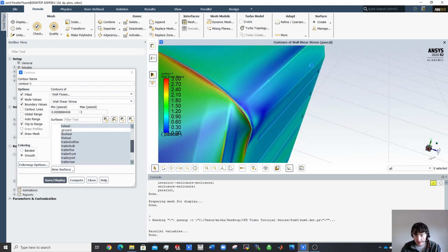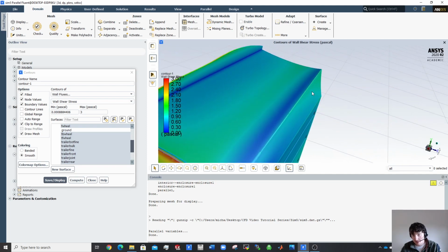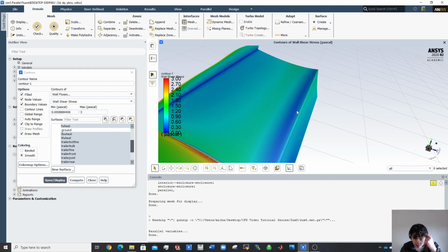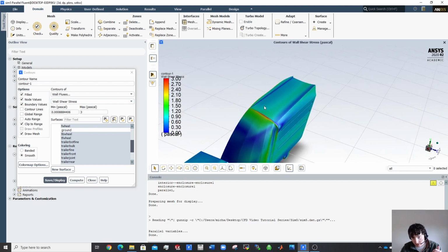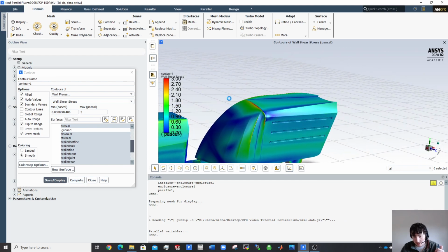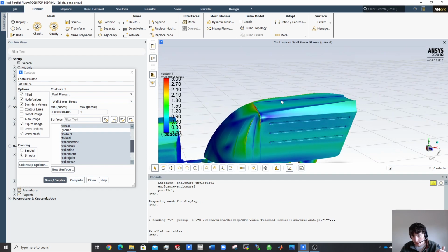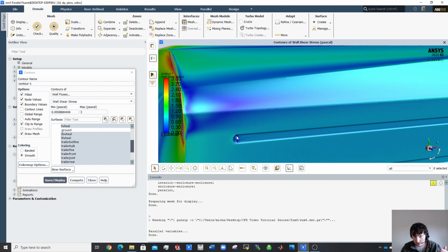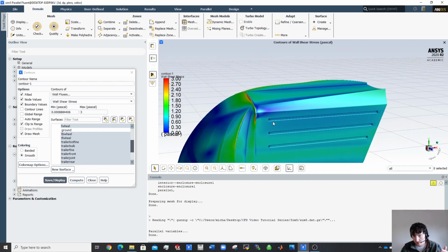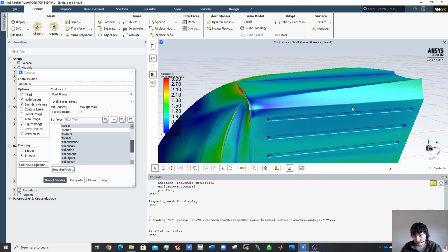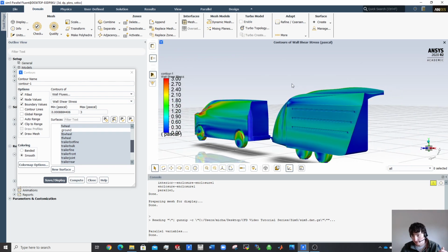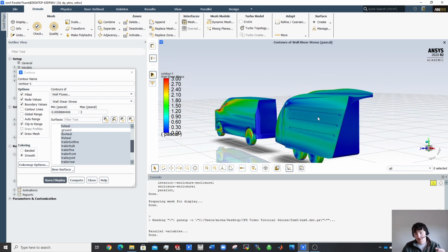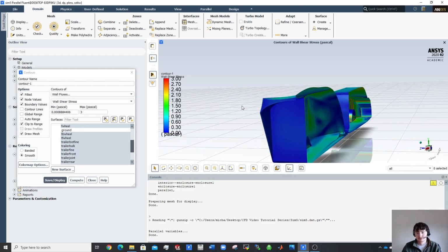But the back here, this side panel looks very good. But I'm kind of losing the flow a little bit here, so I could probably change the shape on that to increase the performance of that. And you can see the stagnation there. But definitely you can see regions for improvement here. So you can think about, well, how could I make sure that the flow is more attached there and prevent pressure losses. So that's what you're trying to fight against.